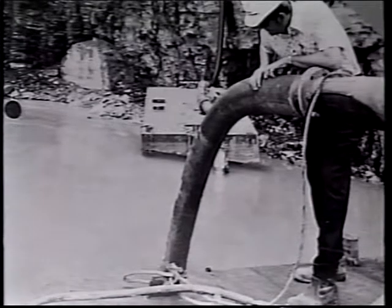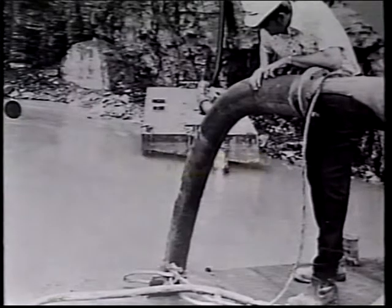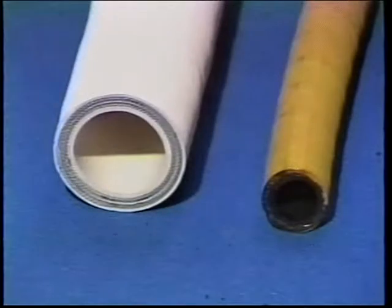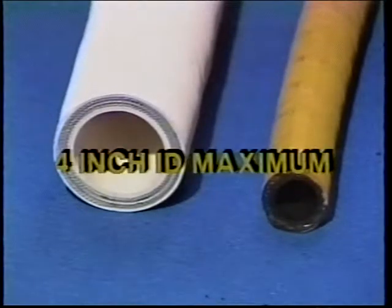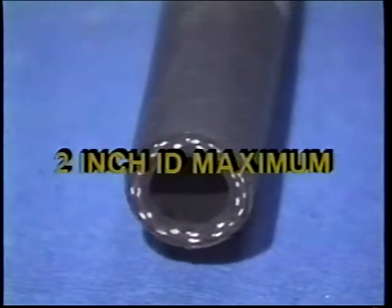High volumes of material may be handled with hose having a large ID. Hand-built hoses are capable of diameters up to 36 inches ID. Machine-wrapped and horizontal braid hoses are usually limited to 4-inch ID maximum, while vertical braid hoses have a maximum ID of 2 inches.